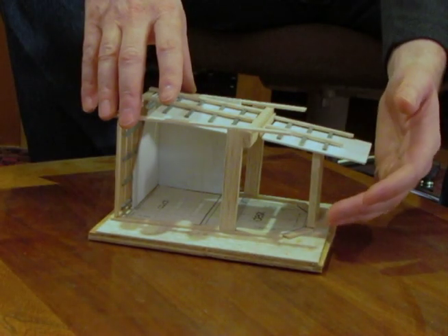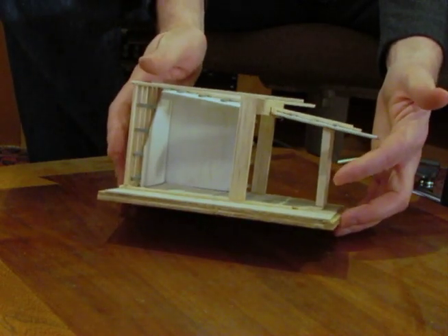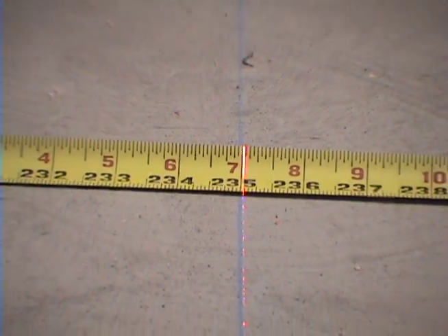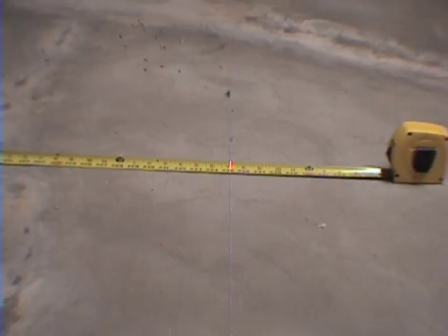Additional support will be had when the walls are built, as the ceiling will lay on top of the wall frame here. From our design, we have a good idea where the front wall of the control room will be, so we can place a chalk line on the floor where that wall might be and use that as a guide for the ceiling.